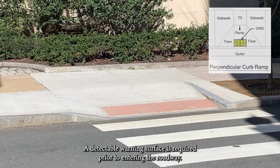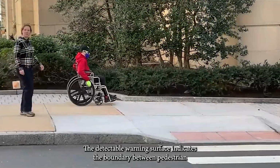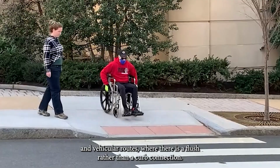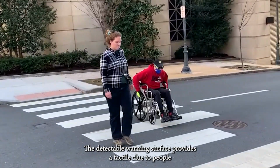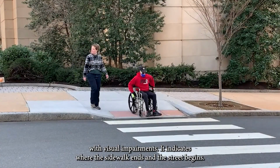A detectable warning surface is required prior to entering the roadway. The detectable warning surface indicates the boundary between pedestrian and vehicular routes where there's a flush rather than a curbed connection. The detectable warning surface provides a tactile clue to people with visual impairments. It indicates where the sidewalk ends and the street begins.